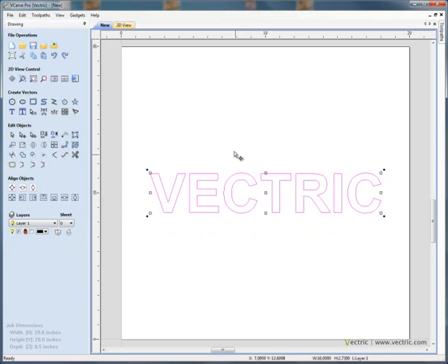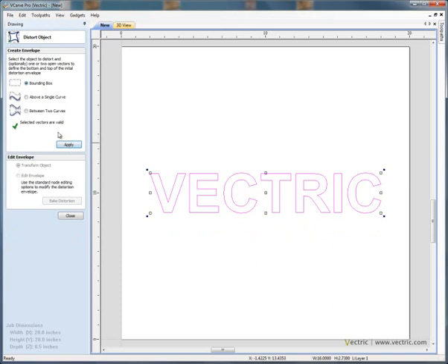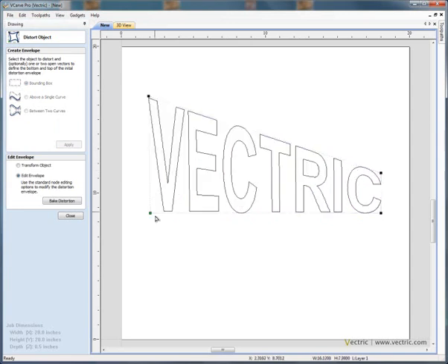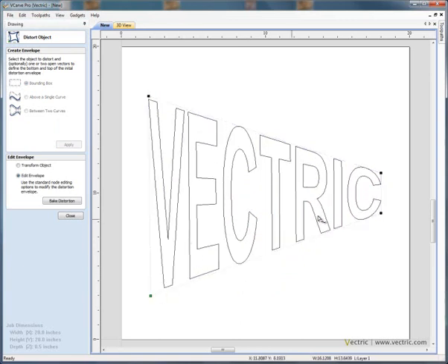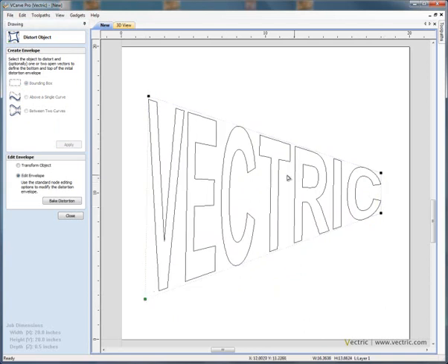Let's just select the text. We can say select, use the envelope distortion tools, and we can say distort the bounding box here. So we could say apply, and we can very easily just click and drag to make the text look as if it's got some sort of perspective being applied, or make it look as if the text is moving away from us. So very quick to just click and drag. We can also change these outer boundary curves, so we could place the cursor over a boundary, and we can use the right hand mouse button and say convert this to a Bezier curve.